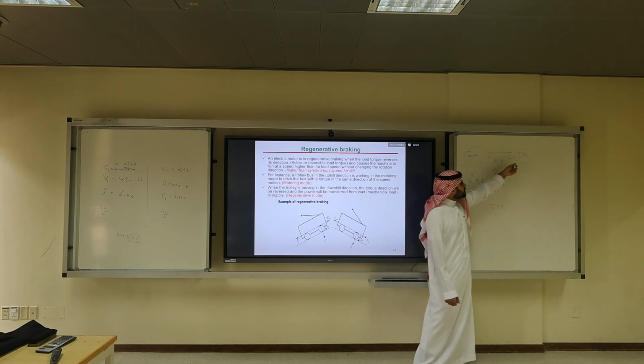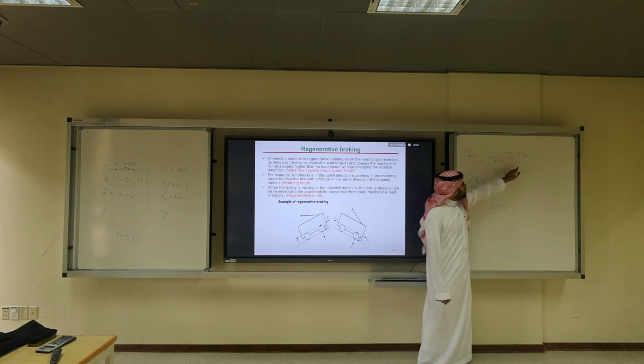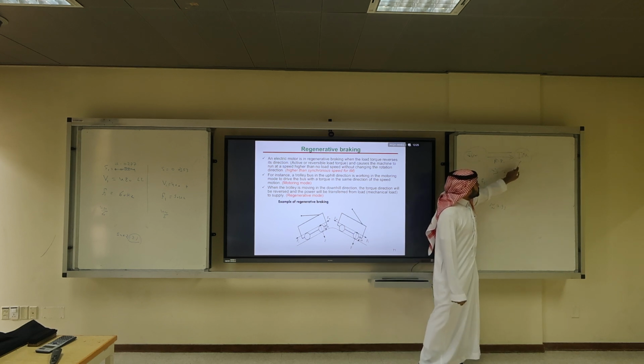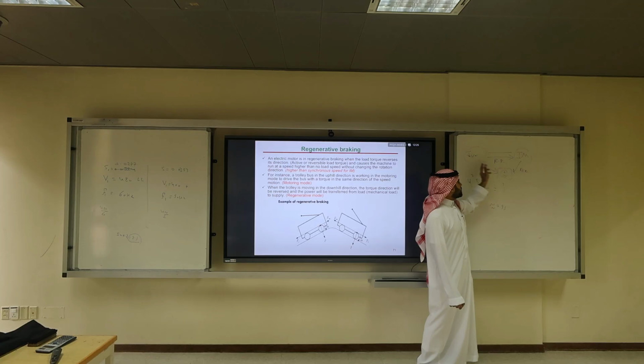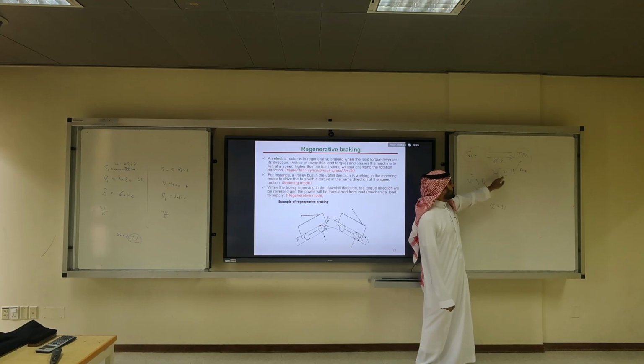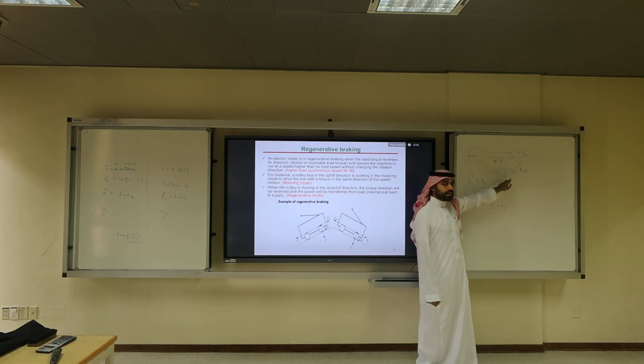Most likely, since the induction machine is already going downhill, the induction machine will do regenerative braking. No, not the tire. The tire doesn't communicate with the battery. The tire will power the IM and it will send power.